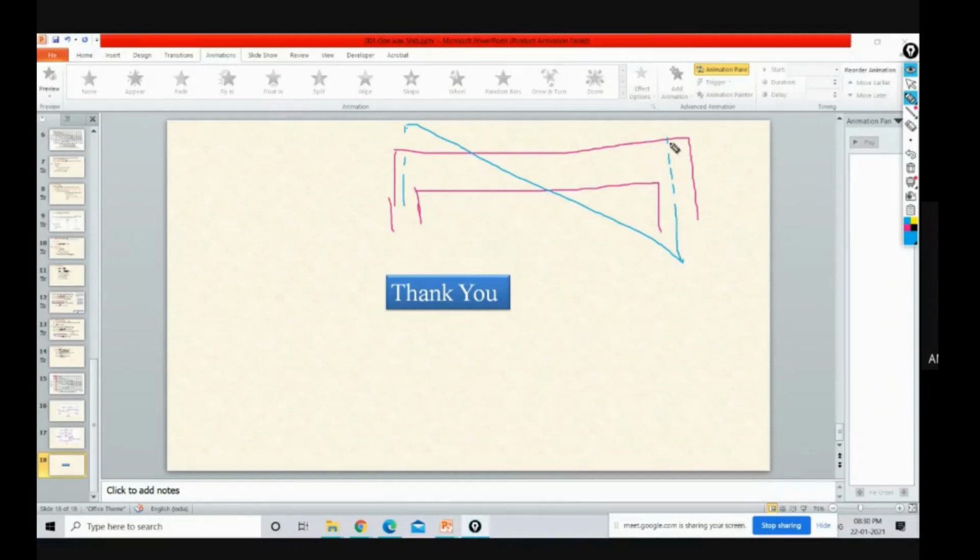Maximum shear force is at the support, minimum shear force is at mid span, correct? So this condition is there, definitely, but generally shear reinforcement depends on your depth also. Depth criteria is also there, correct?